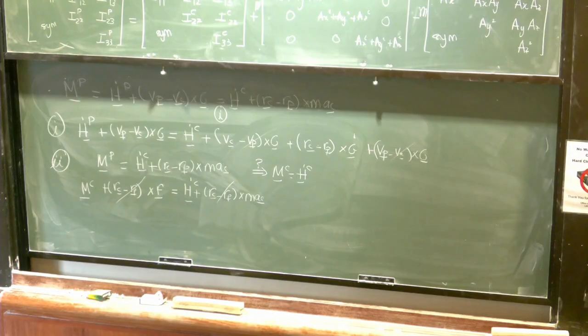So I've basically shown that the two expressions in C for the angular momentum side are equal, and A and C are equal. How do I show that B and C are equal? It's also pretty simple because P is the general case of any material point on the rigid body, and O is a special case of that material point having zero velocity, right? So if I look at equation C, and if I take P to be O, where VO is 0, do I recover B?